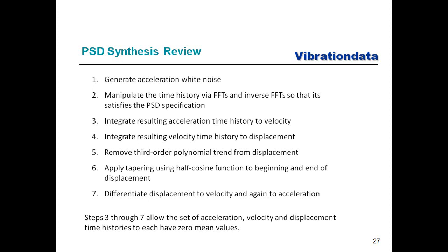So for step 7, I take that displacement from which the third order trend has been removed, and also with the tapering. When I say tapering, if any of you have played around with acoustics or sound processing, in the acoustic world that would be called the fade in and fade out.